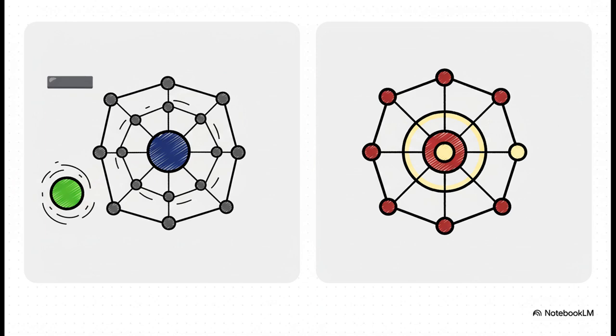First, you can add impurities that have an extra electron hanging around. These are donor atoms because they're happy to donate that electron, which creates what we call N-type or negative material. The other way is to add impurities that are missing an electron. They're called acceptor atoms because they create an empty spot, a hole, that's ready to accept an electron. And that gives us P-type or positive material.